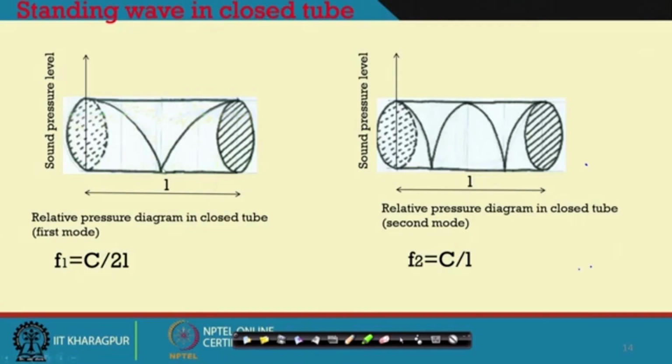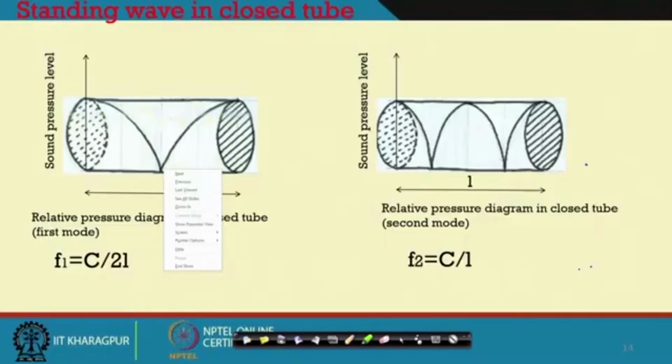And what will happen at the wall side? The sound pressure level will be maximum over there, and as you have seen in my earlier slide, at the center those sounds will not be heard, the pressure level will be minimum. So, at the wall side, the pressure level of these particular frequencies which by chance get to be a multiple of this room dimension will end up into the room mode.